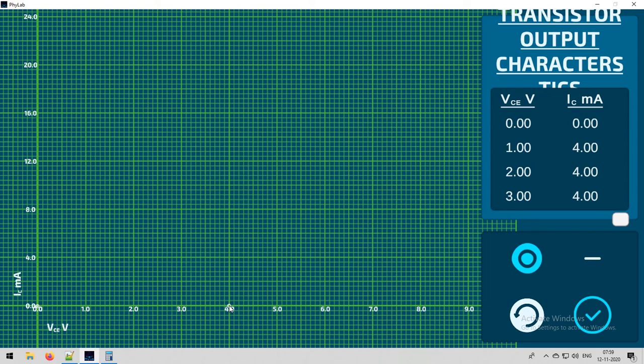So dividing voltage by current, we get the input resistance. So we are done with input characteristics. After that, you need to perform the same operations. Prepare a graph for output characteristics.